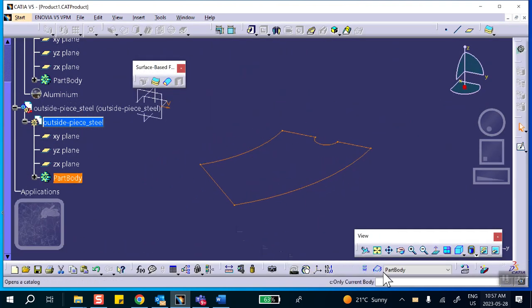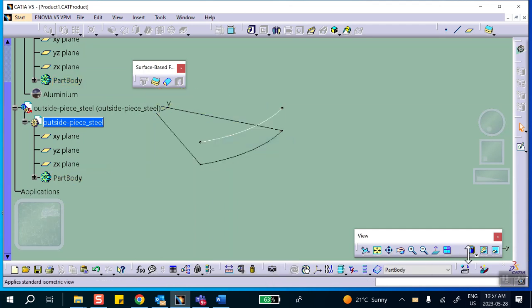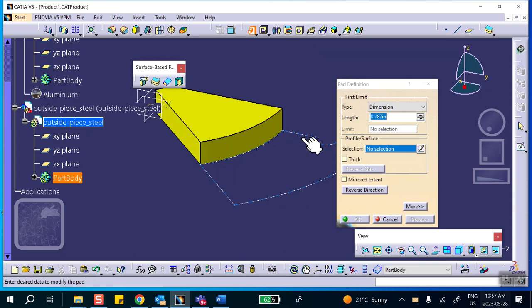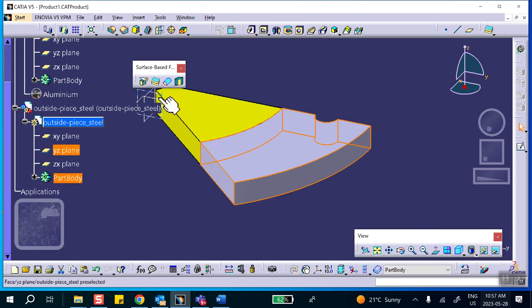All right. Now, if you want to see the other piece which is hidden, it's right there. Let me bring it in the front so you can see it. We're going to pad this thing up by 0.5. Now, once again, I want to remind you that I could have drawn this yellow piece with that distance being 3.001 instead of 3, but I used the nominal one.